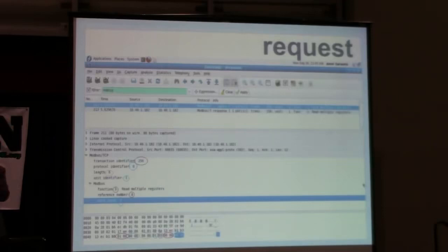And by the way, we didn't have to modify or write plugins for any of the packet sniffers. So what usually happens is if you are debugging a new or unknown protocol, the packet sniffers cannot sniff the packets because they don't know about that protocol. But most of the packet sniffers, actually I would say all of them, Wireshark or any of them, already have built-in support for Modbus and a lot of SCADA protocols. So if you do this in your environment, you wouldn't have to do anything special. You just sniff the traffic, and it will show you clearly what's being sent.